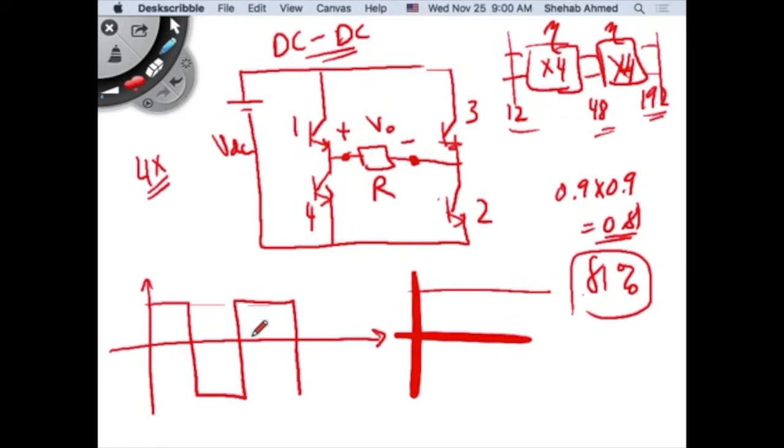If you put DC across a transformer, the winding will not generate back EMF to oppose the voltage that's being placed on it. If there's no back EMF voltage generated to oppose the voltage that you're placing across the winding, meaning it will look like this, a voltage source in series, that's the equivalent circuit of a back EMF voltage developed across the winding. If the winding is not going to do this, then what's going to happen? Then you're placing a voltage source across a piece of wire, basically.